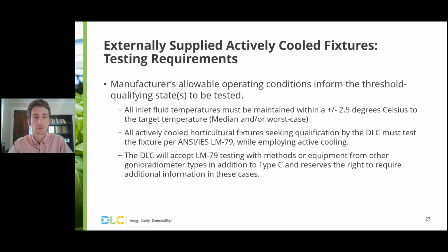And then regarding those temperatures, the target temperatures, so that's the median temperature for the LM79, and then the worst case temperature for the ISTMTs, they must be within 2.5 degrees C of the target. Additionally, the LM79s must be conducted according to IES standards.